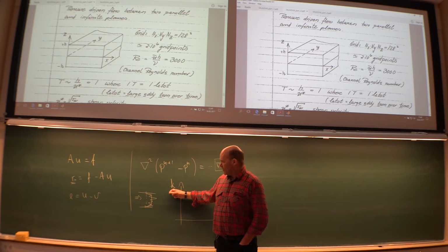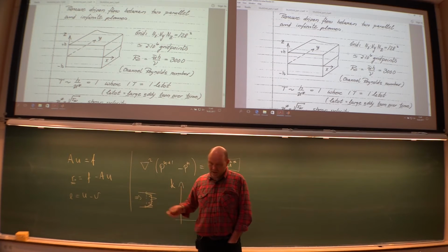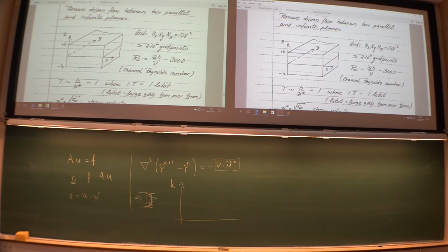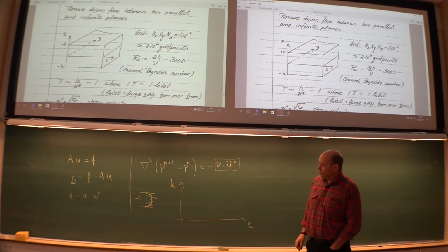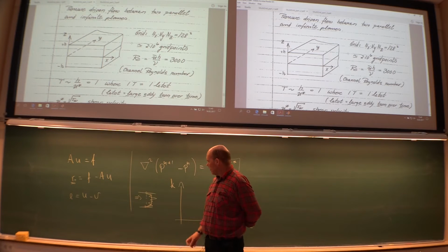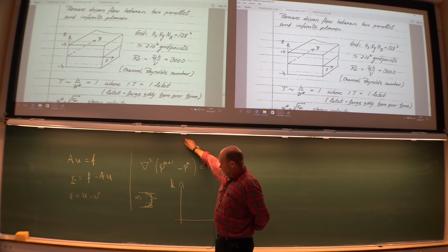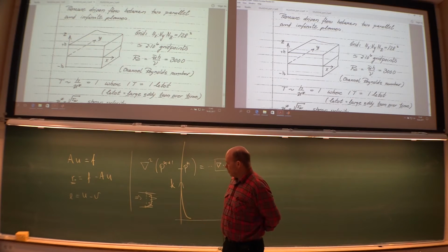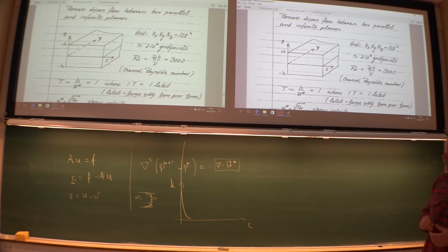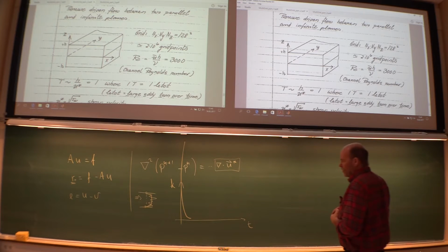But this one was now averaged for the entire volume. I had to do it in 3D. The turbulence is by nature three-dimensional, so you have no choice. Full 3D. So I calculated all the kinetic energy, and then I plotted that versus time. What happened was, since I used a random generator initially, which just produced a lot of noise, which was unphysical, it was sky high. But then after a very short time, a couple of time steps, it was reduced to almost 0. And that's due only to the continuity equation, damping out all these random velocities and pressure, which was very unphysical.